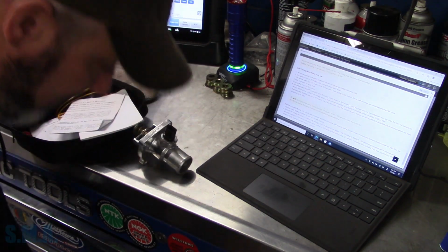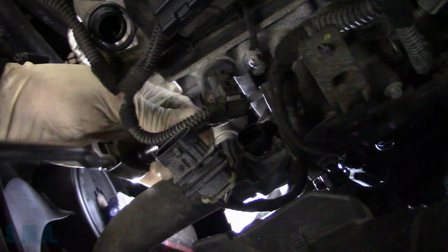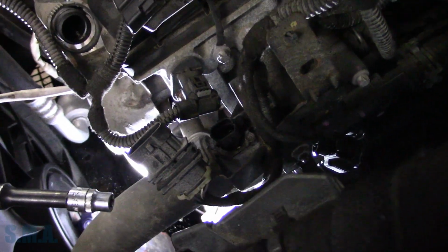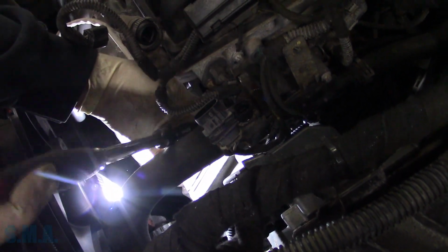And we'll go over here, see if he's got a drain bucket under it. And, oh, I put that right in the drawer. So the thermostat housing itself is held on with 4 bolts, and they're inverted Torx. Looks like those little guys right there. So I'll get them out, and then the coolant will drain here momentarily. So have a bucket ready.